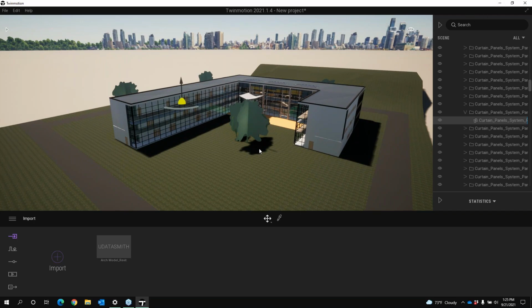So without opening up Revit, the second thing I want to show you, and this is what I figured out in the process of the project that I used before, especially with curtain walls, because a curtain wall or any system in Revit, whether it's stairs, curtain walls, even certain wall assemblies and things that have multiple sweeps, technically in Revit, they're kind of one element with many parts built into them.